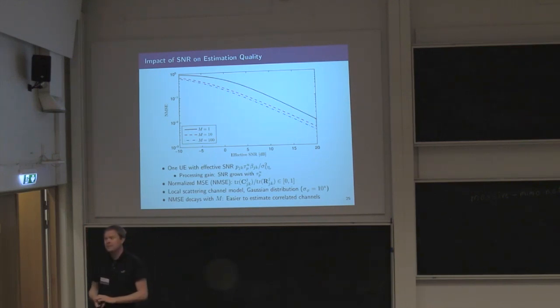Well, I want to talk about the selection of MMSE estimation. As you told, these channels are correlated, so they must be dependent on each other somehow. So the recursive algorithm must perform well in this scenario. Yeah, so I am not exploiting any information between coherence blocks here. But if you do that, I guess the better your estimates are here, the more prior information you have, the easier it will be to apply a Kalman filter or something like that. But I haven't looked into that myself in a correlated case.